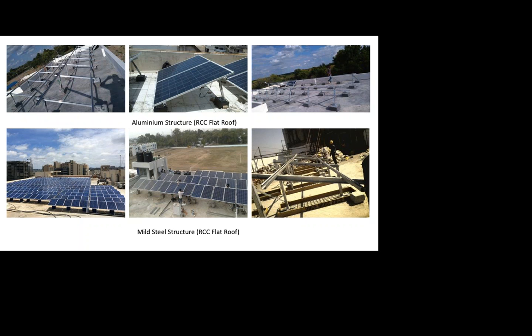Now in the Hilti options, we have considered the same kind of structure. Just 1 second, Gurpreet. I see that because of Hilti, the cost of the structure is going very high. When we are doing aluminium and ballast, it is 4.7 rupees a watt. But if you're doing aluminium and Hilti, it is 6.6 rupees a watt. There is almost a 1.9 rupees a watt increase just because of the Hilti. Does Hilti warrant that we should spend about 1.9 rupees per watt extra?